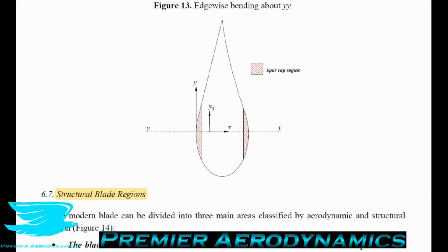It's usually within about a 2 to 3% range of that, which means that when you do your experiments, you're getting a 2 or 3% error in your results for no good reason. You can get rid of it very easily. And that also makes CFD harder to validate, because your CFD doesn't have the same density as what you measured your experimental results in. So of course they're not going to line up.